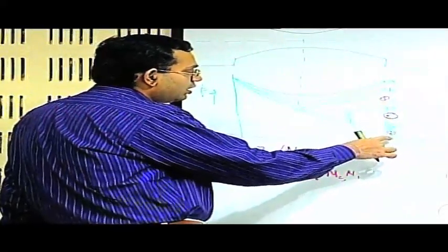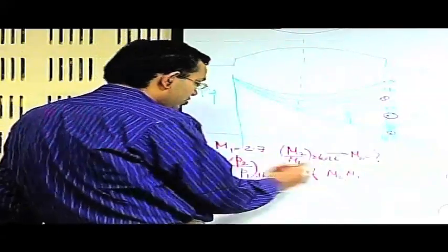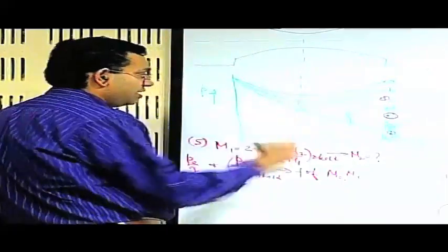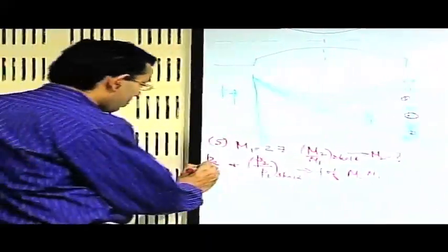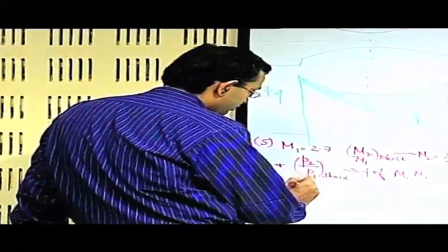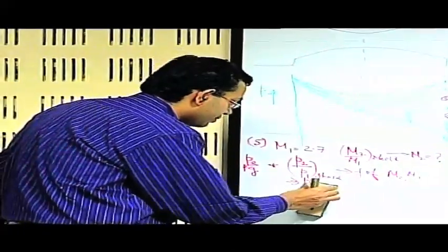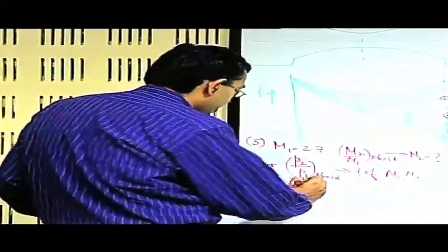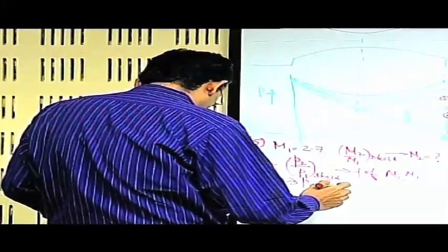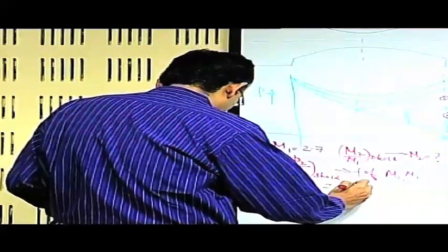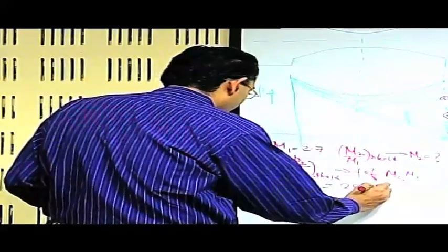and from there you can find the pressure at E, because you know the pressure at G. So P2 by P1 is as good as PE by PG in the figure. So from here you can find PE, sorry, not PG. So that value of PE for this problem, the answer will be 286.5 kilopascal.